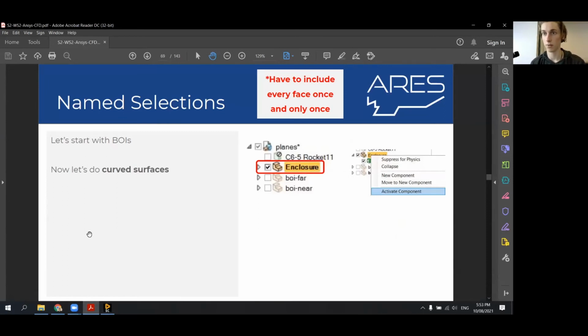This is another really important thing. You'll find that it doesn't mesh curved surfaces very well, so you have to apply specific extra instructions to the mesher for curved surfaces to say, hey, I want you to actually model this curve instead of just turning it into a 45-degree angle. I want it to be nice and curved.